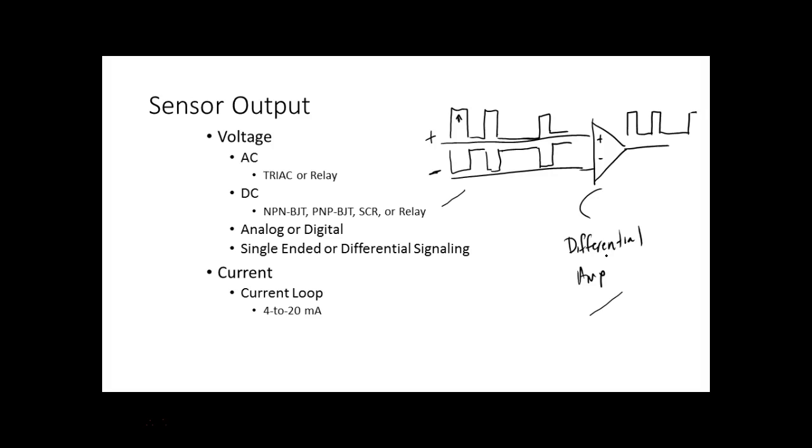So what that means is if I had electromagnetic interference come through in here, it would induce a voltage into this guy, and it would induce a voltage into that guy, right? But these guys are moving in the same direction. This is what became known as common mode signals. So this amplifier only lets differential signals come through. These guys right here would be common mode, and it would block those. You can actually see this. They call it a common mode rejection ratio.